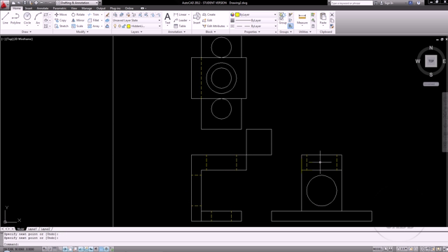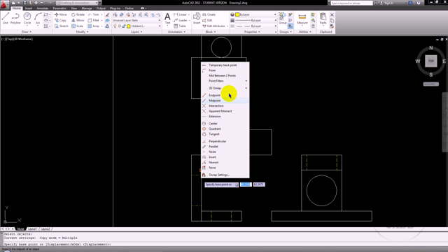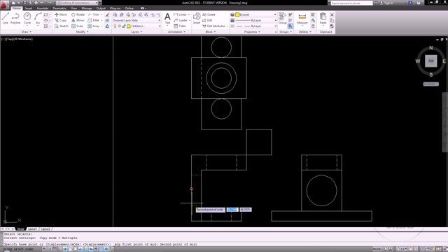And then, much like I did for these 2 hidden lines, I'm going to do the same thing for these. So I'm going to copy these 2 lines, select enter, shift right click, mid between 2 points, and I'm going to grab right here, and just pick that midpoint.